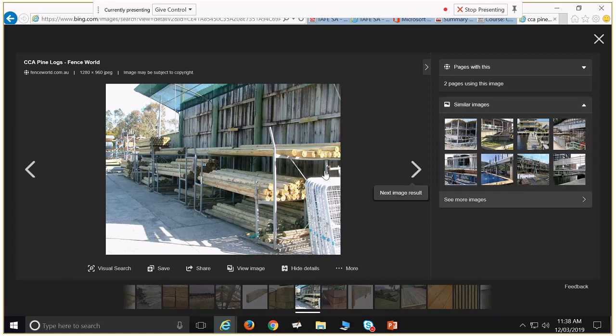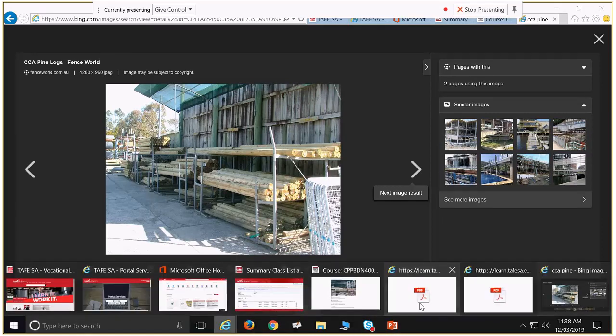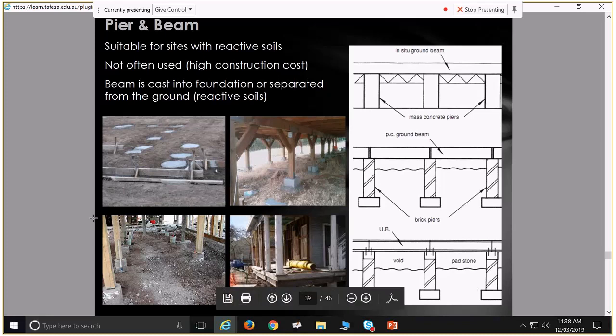But for many scenarios, you're going to be looking at doing concrete pads or concrete piers underneath your exposed piers above ground. You're going to be looking at a scenario like this, where you have some soil removed, you fill that with concrete, and then you provide a level, very strong footing to that pier, because concrete is very reliable. We can mix up concrete to be 20 MPa concrete or 32 MPa or 40 MPa concrete. We can say what the megapascals bearing capacity of this concrete is. That can be fairly easily controlled and determined.